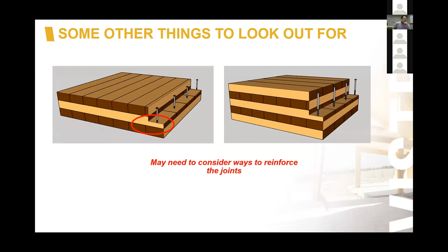Some things to be mindful of. If you're looking at a diaphragm and you've got a very thin floor plate and you're looking at just a lapped connection, the way that a CLT panel is made is by gluing the faces, typically. It's not the edges. Not many manufacturers actually edge glue their panels. So to get load transfer across that joint, you're relying on a very thin throat of a fibre in the primary direction. And then the lower board potentially has a joint in it.